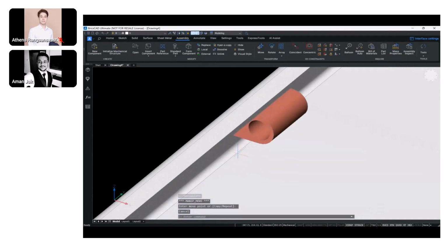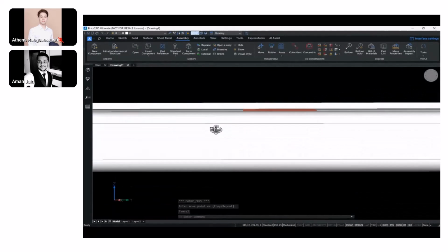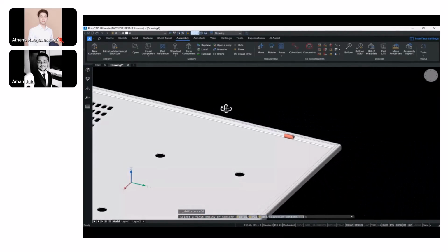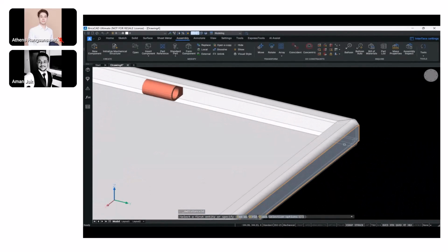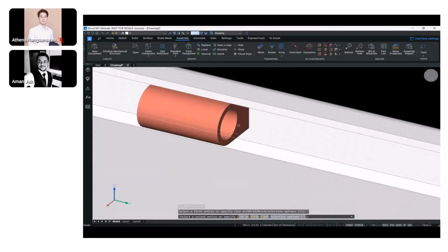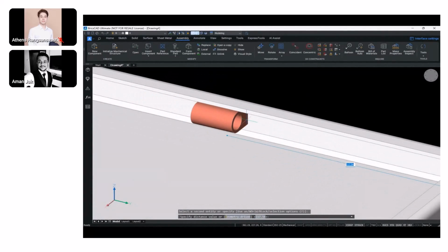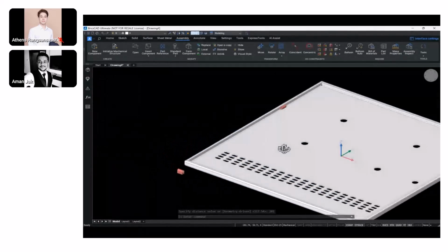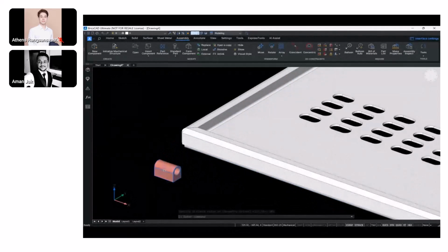So I can just move it across, and now it's freely movable across the y-axis. And what I can do is now give it a distance constraint from the outside side of the door to the flank or to the hinge at a distance of 200 or 201, because we need some clearance when it'll get mated with the hinges present on the body, right?